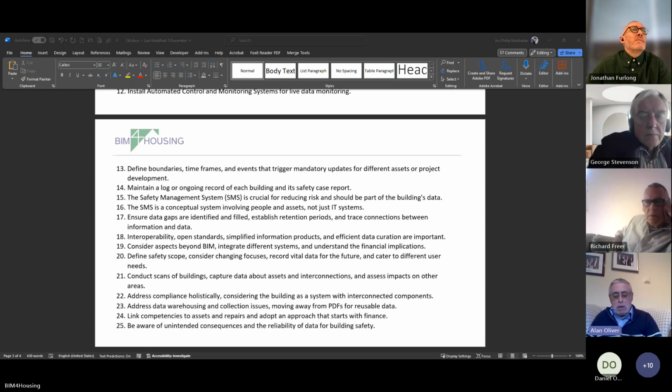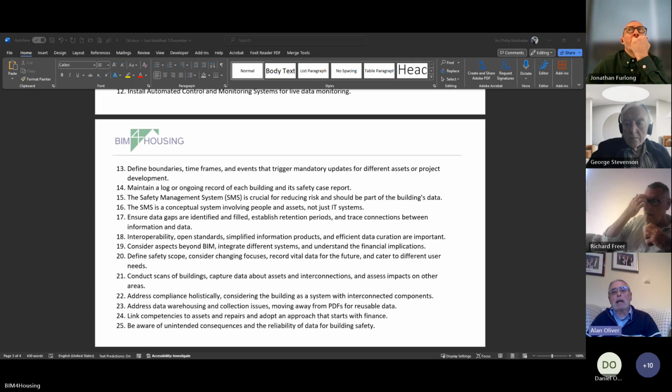Okay, so taking that background aside, what we're saying is with existing doors that are unlikely to be perfect, and where you haven't got a golden thread of information, some of them might be more than 30 years old, you've got to take a pragmatic risk management view. And one of the things you have got to do is look at the fire doors in the context of everything else in that building, and the size of the building, and the complexity of the building, and the level of risk of that building.